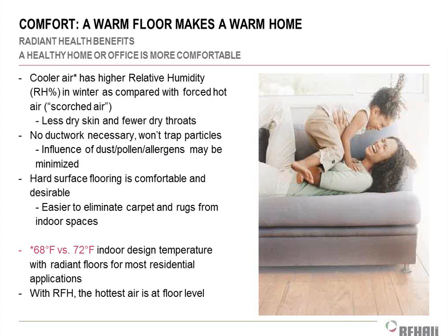So if I keep your stat set at, in Matt's example, 62 instead of my house, which is a furnace, and I keep it at 69, right? If I keep it at 62 instead of 69, the relative humidity percent is actually higher, and I feel that difference, right? So there's not as much static electricity, not as many dry throats and dry noses and that kind of stuff. And so I'm not even adding a humidifier. It's very rare for us to do a residential radiant system and add a humidifier to someone's house. Generally, we don't need it. We may need an ERV to bring some ventilation air in, which is a whole other discussion, but I generally don't need to add a humidifier. Right, so that's kind of the goal there.